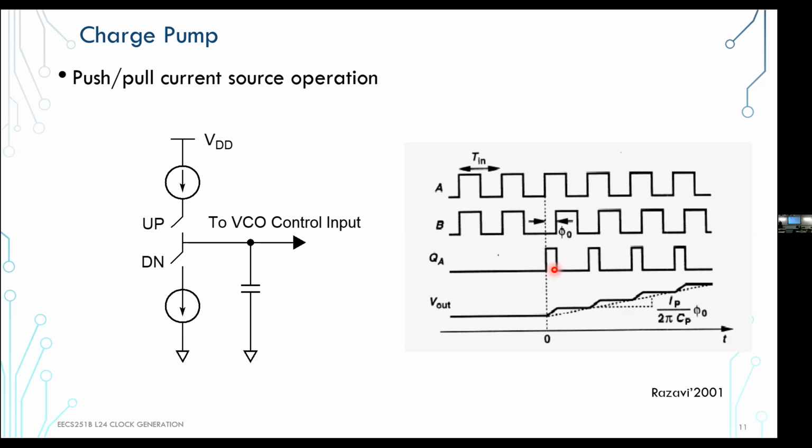So this is a little diagram that shows that. For every pulse, we do a little integration, and then there's nothing, and then there's a little bit of integration, etc. So overall, there's still a little ripple, a little staircase, because after all, this is a sampled system in the sense that every ref clock, something happens on the input. And so you get these little updates.